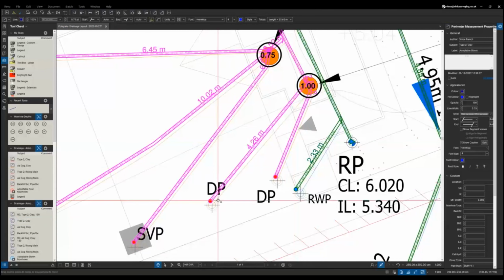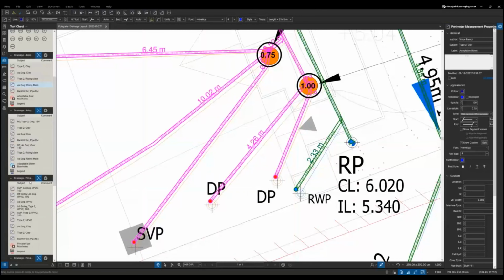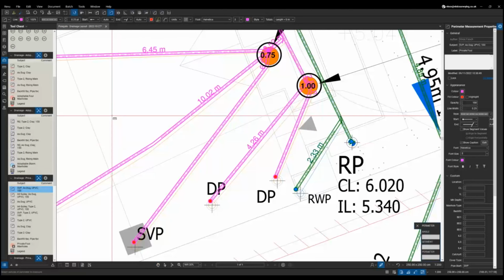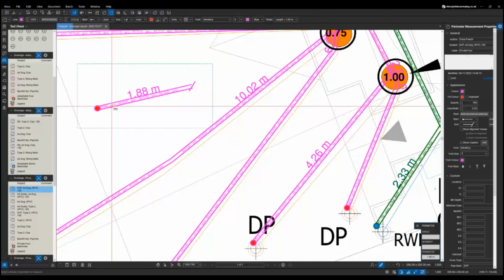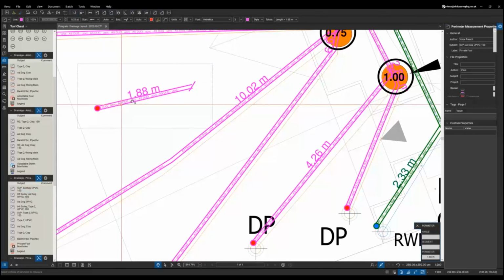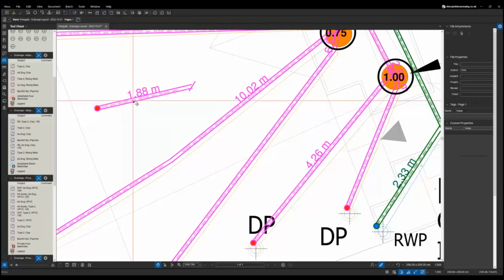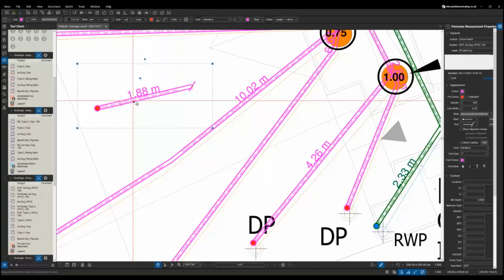This is my plot file, and what you will see is I've got custom tools for this, and if I jump over here, my custom tool, if I just mark that up, you'll see that I use a symbol at the end to represent the saw vent pipe, and it brings forward details. The markup shows details like it's a UPVC pipe and it's as dug backfill. That's just to try and make it clearer for whoever else picks up this drawing. They can zoom in and out and they can see what's been allowed.